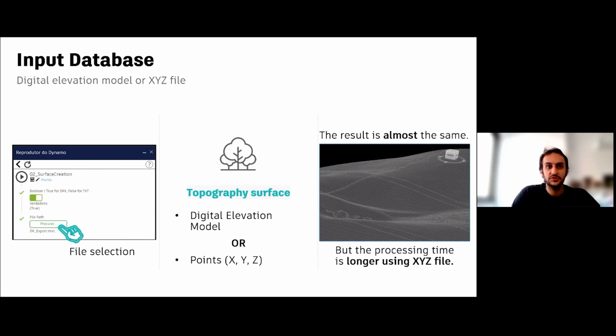We also know that this processing typically takes time when terrain elevation models are heavy. However, we do suggest pre-processing the surface with InfraWorks or similar software to convert the digital elevation model format into IMX format file. Using the IMX, the user will save time in processing within CV3D.